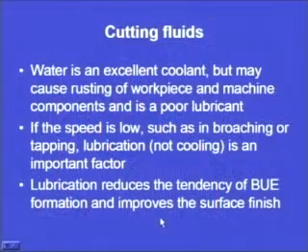Then lubrication reduces the tendency of built up edge formation. If we are using a lubricant, or a cutting fluid which has the lubrication facility, then it will reduce the tendency to form a built up edge, and thus it will result in an improvement in the surface finish. So, if we are using a particular cutting fluid, then the chances of built up edge formation are minimized, and the problem areas associated with built up edge formation can also be countered.